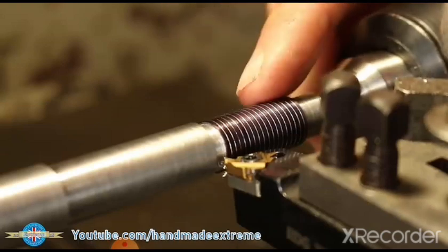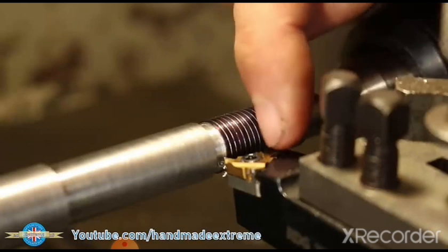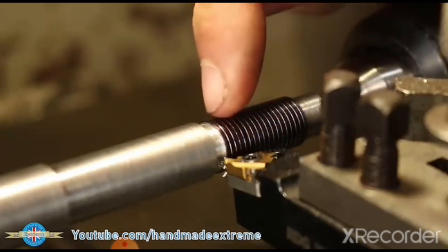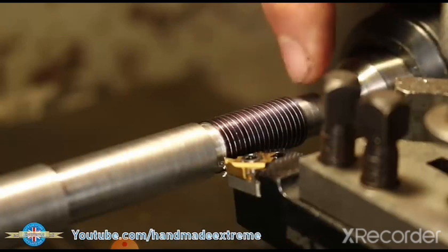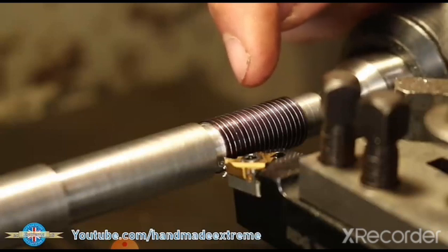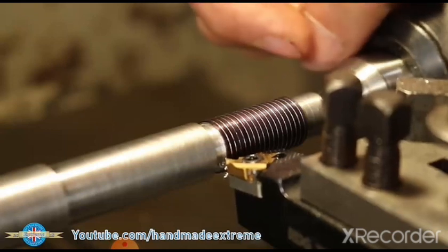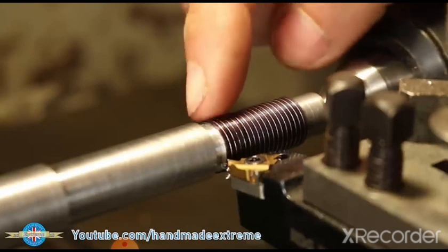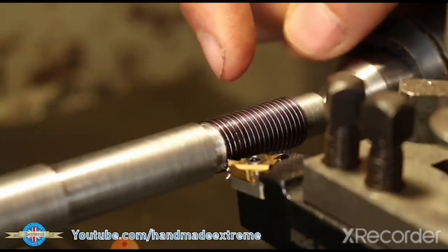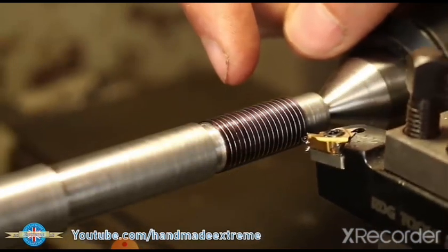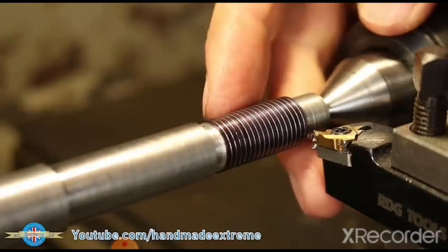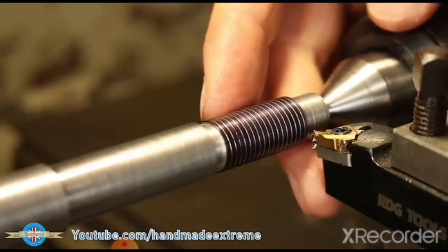What you mustn't do at this point is just bang the machine in reverse and send the tool back the other way, because of the backlash in the lead screw, you'll end up cutting a different thread on the return pass. So the way around that is that we withdraw the tool in the X direction, or the negative X direction in this case, so that it clears. We've already disengaged the half nut, so then we can just wind the tool back to the start. Of course, because we're using the half nuts and we can move the carriage independently now, you can leave the machine running while you're doing this.